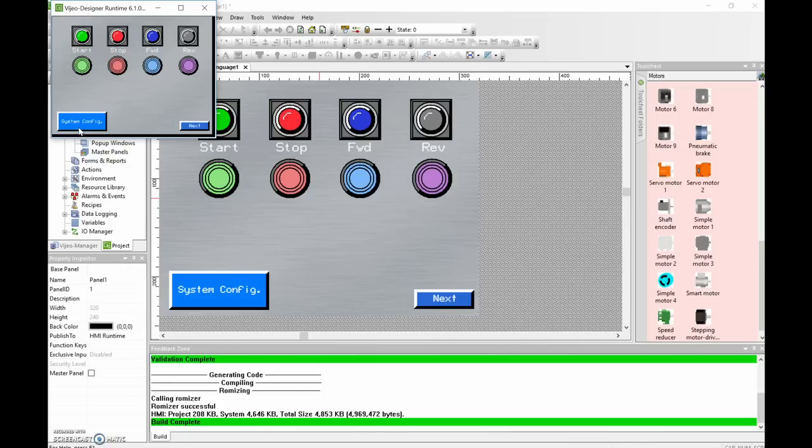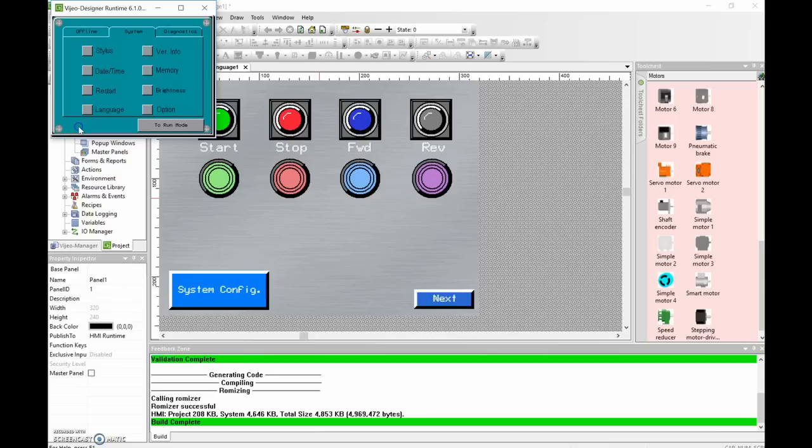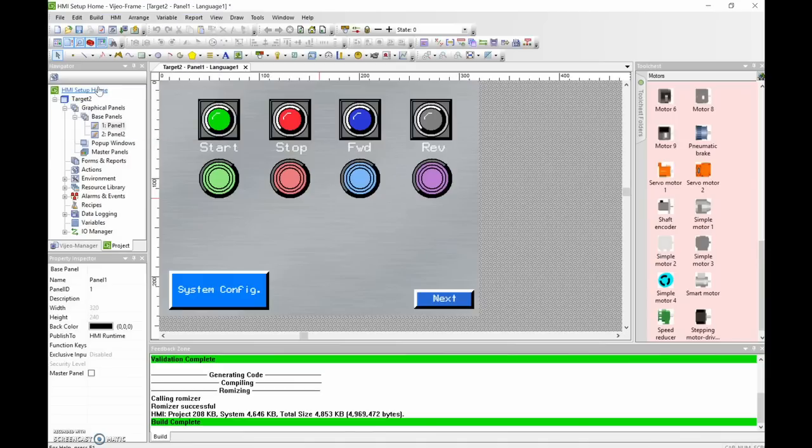You're supposed to be able to press both sides of the touchscreen with your fingers and be able to get to the system config to set up your IP. It wasn't working for me. So we're going to put a push button right here so that when we need to get to our configuration and we need to get to our networking, then we can actually get to our IP address and change it if we lose that communication. Then we don't need to talk to it by USB or anything. We can keep using the Ethernet communications. So let's close this guy up.